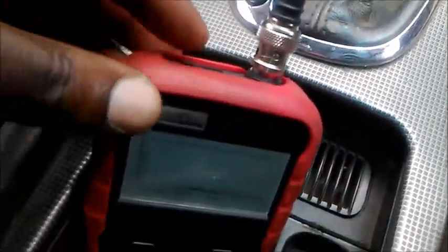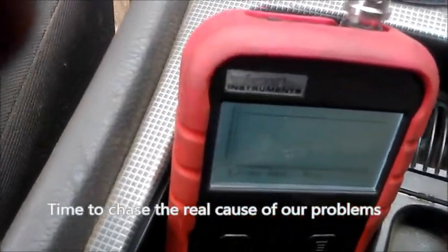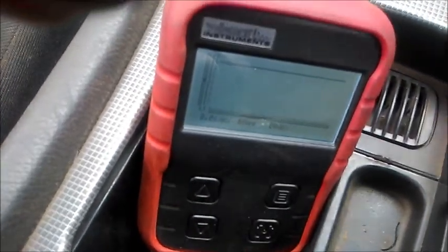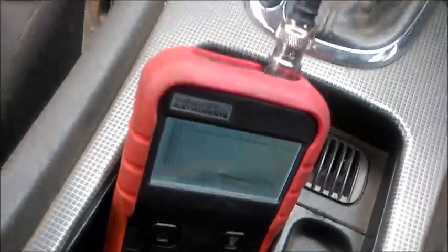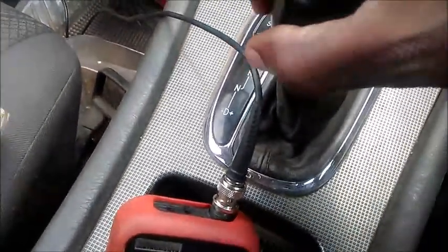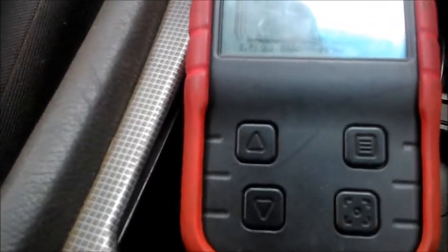Okay, with the engine running, I'm now on our suspect speed sensor, and want to engage R. I'm now in R. The signal is not showing any change.